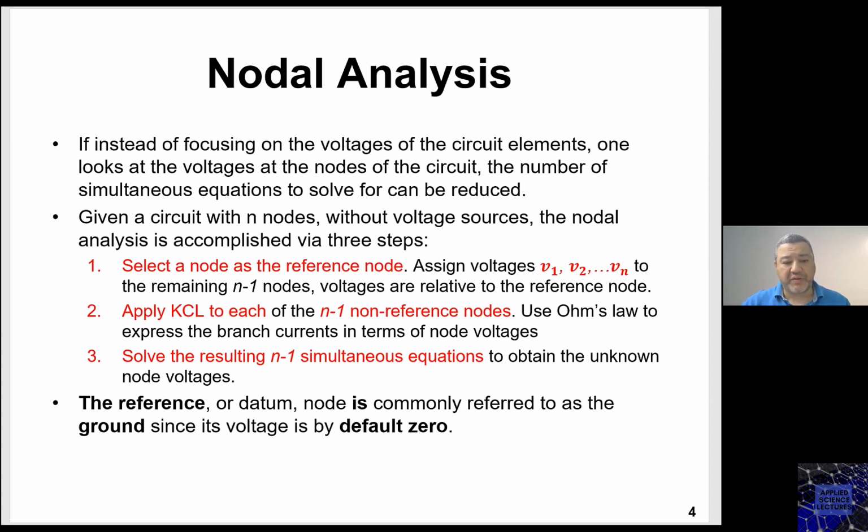Here we are proving the nodal analysis approach. We will be developing those equations first, showing you how we came up with the nodal equations technique and how to write them, from scratch. Nodal equations are KCL based, so we'll be relying on KCL in order to derive those equations. Once we identify those nodes, the total number of equations we should come up with is n minus 1. So how do we do this? We will see.